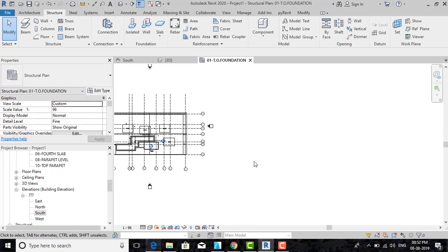So we have to model one load bearing wall. How to make that? A load bearing wall will not be a straight wall going from the top of the foundation till the hard strata. This load bearing wall will be in the form of a step foundation. It will be like a step foundation, but the material will be brick. Let me show you an example of this section.